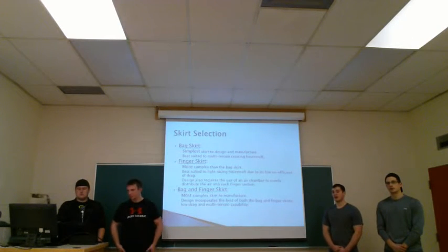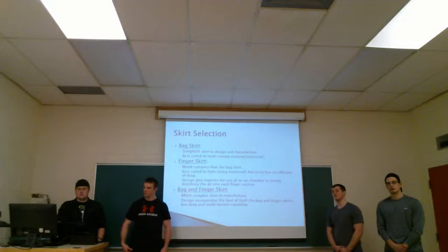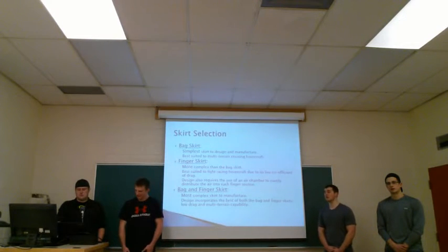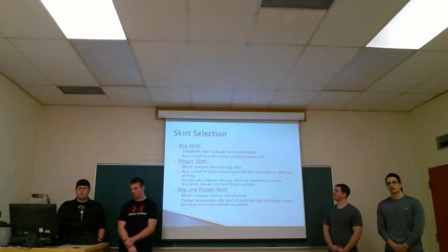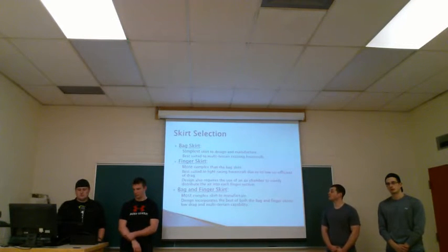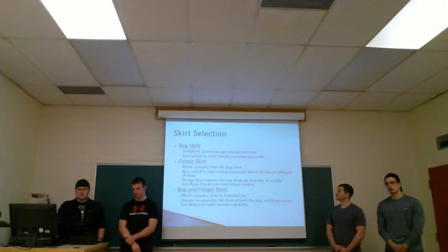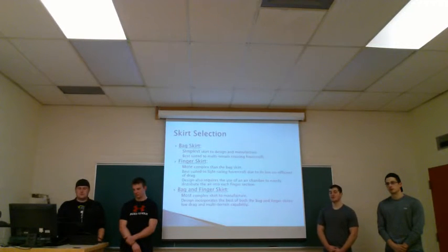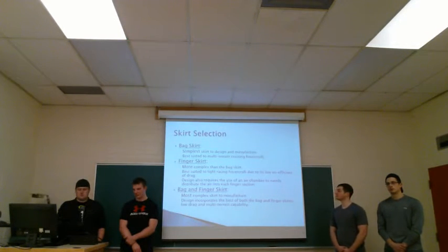Our finger skirt is a little more complex. It will take a lot more time to design and build a finger skirt. The finger skirt is best suited for light racing hovercraft because it has a low coefficient of drag. The design also requires the use of an air chamber to distribute the air into each finger of the skirt.